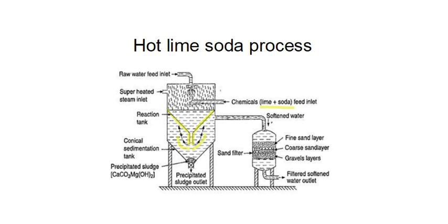One is the reaction to convert the hardness into calcium carbonate and magnesium hydroxide, the formation of these two species. And second is the growth of the particles in size so as to come down with gravity.